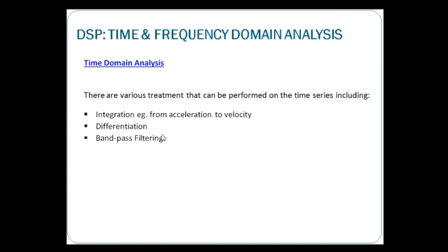Of course, your anti-aliasing filters are analog low-pass filters, and that part is already built into the hardware on your DAQs. That is to take care of all these wrong representations of our time signals.